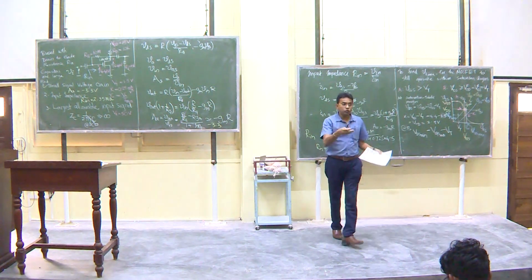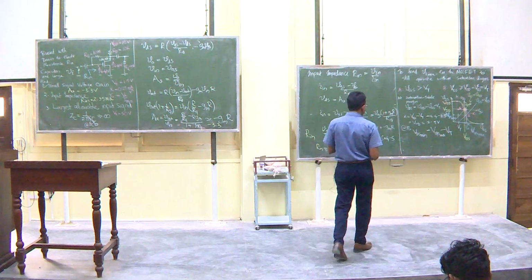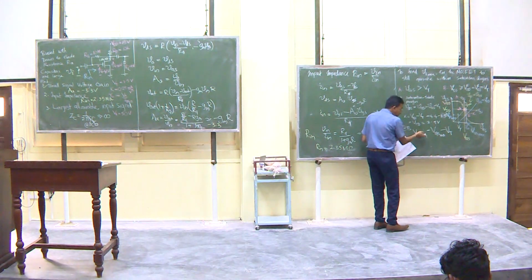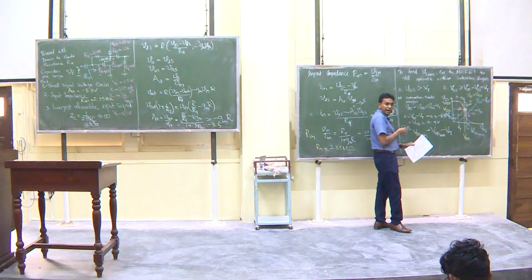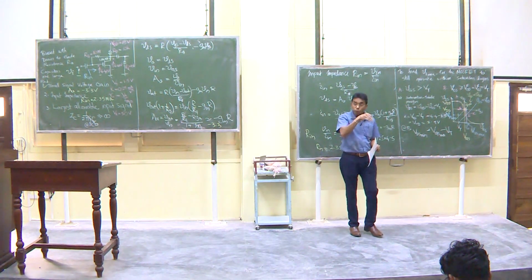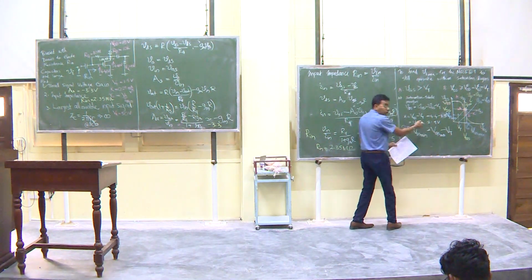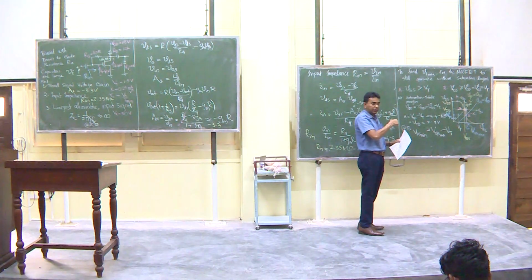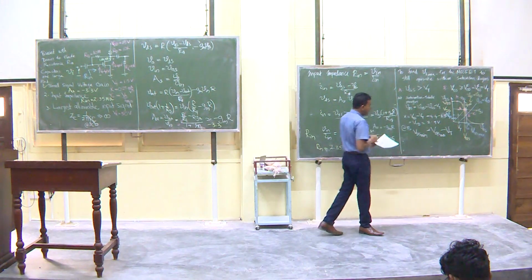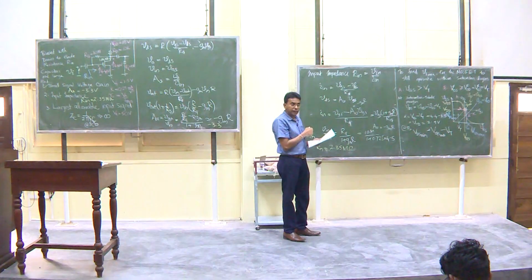This is from the VDS equal to VGS minus VT equation, right, because this is the saturation margin. Otherwise it should have been greater than or equal to, but this operates exactly at that point now, because it is on B. That is why this is equal, otherwise it should have been an inequality sign, but I am operating at the equal sign now. So, therefore, this expression is correct.